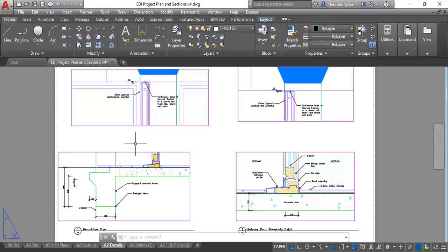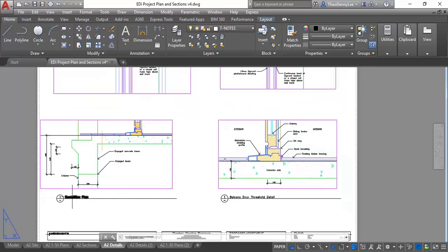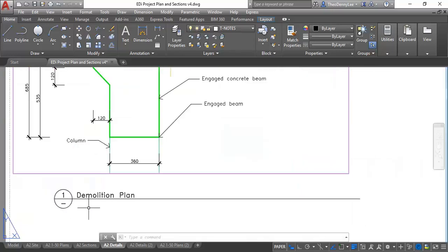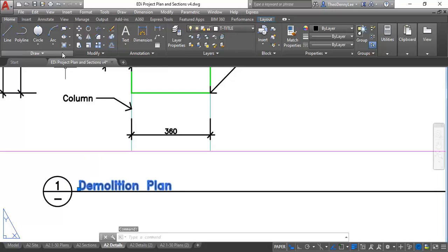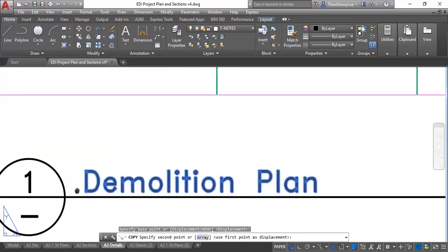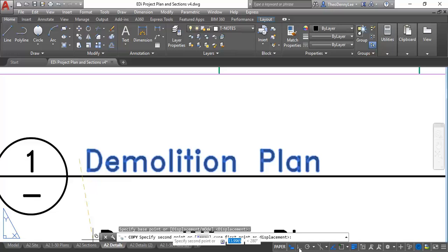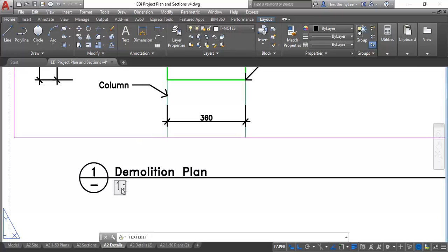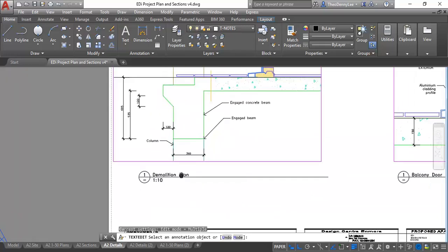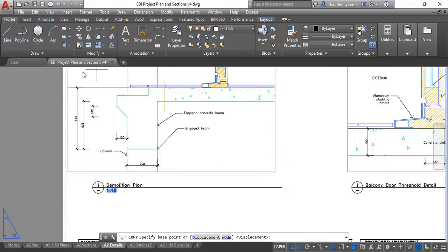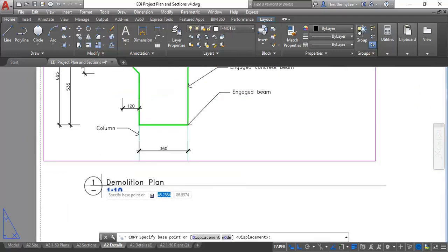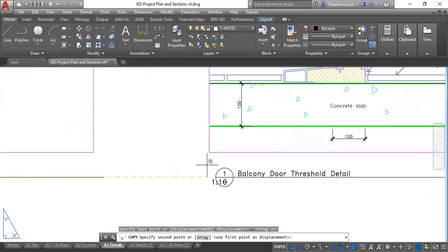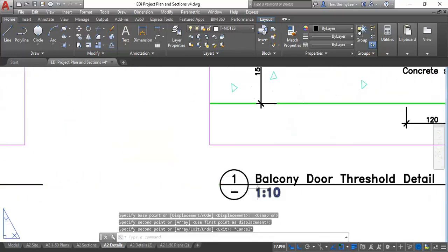Yes, absolutely, spot on. The viewport should have the scale, the label for each view, in other words, should have the scale. I haven't put that in yet because it's still a work in progress, but you would always, in the end, have the scale below the name of each view. So this one is 1 to 10. Because usually you're going to have different scales on the same sheet, and so you can't just have the scale in the title block. So this one will be 1 to 5.